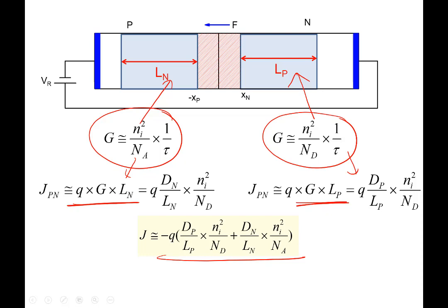But now you think about it. So let's look at electron current. So we are saying electron-hole pairs are generated here, right? Okay, so the electron current comes here. But aren't electron-hole pairs generated here? They will be generated here also. So what will happen to those electron-hole pairs? That electron will also come out here along with it. So what is the total electron current? Total electron current is the one that is generated here plus the one which is generated here. They add up. Similarly, the holes come here, but electron-hole pairs are generated here. This hole also will come here. So together they will come out.